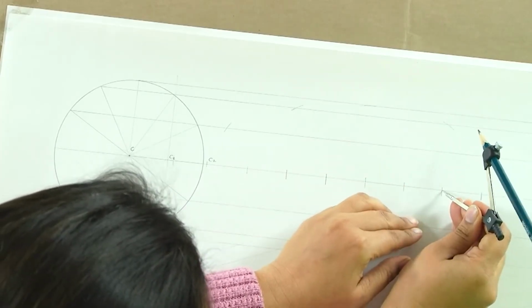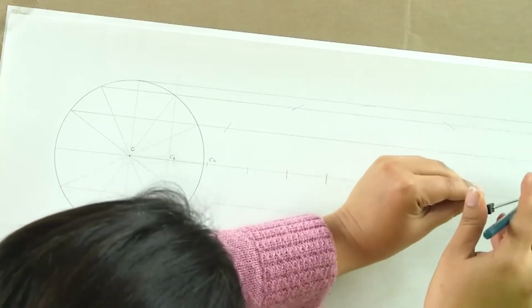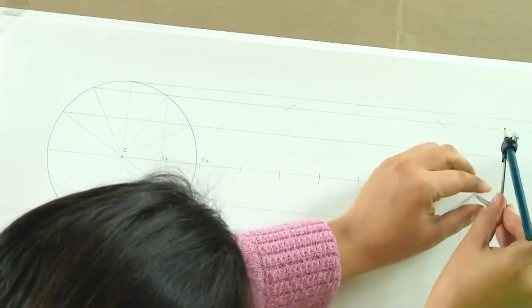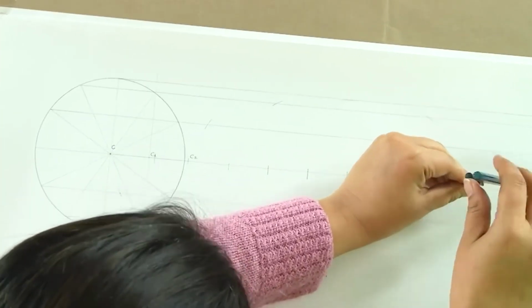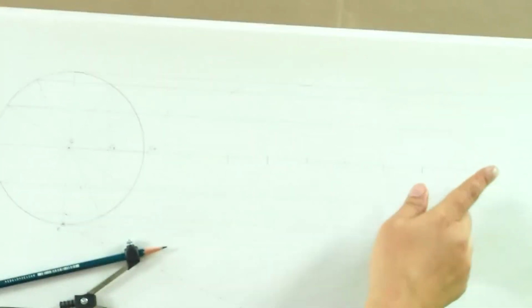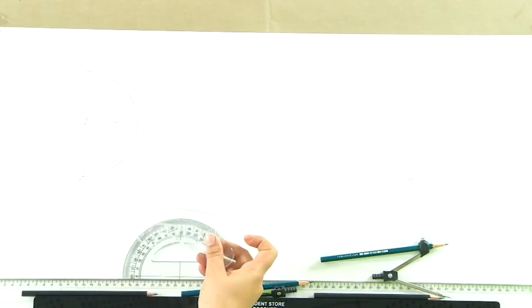And if you can see, we can very clearly note that the path of the cycloid is almost traced. You can complete it like that, and then we will darken using the French curves. So, we can see that the cycloid path of the point P is almost traced, and what we have to do next is a little difficult task, which is to fix these curves.